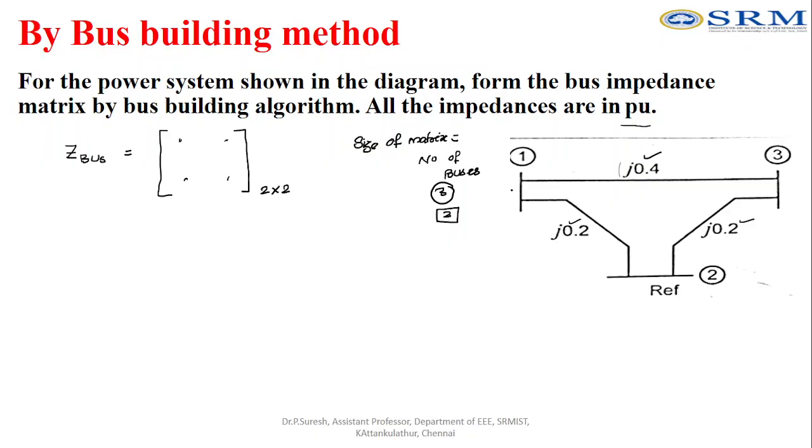In order to generalize this, I will take those values as start bus J and end bus K, JK. So J is 2, K is 2, so a 2 by 2 matrix. If you take the elements here, I will take J here and K here, J here and K here. Actually JK is representing the bus numbers. So we are going to construct the bus impedance matrix, right?